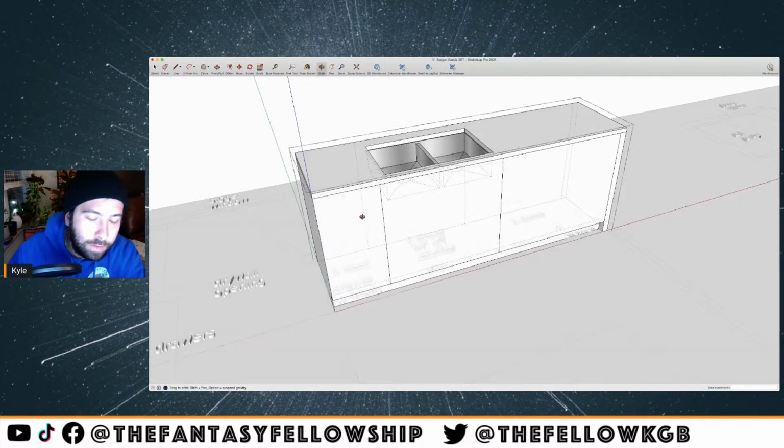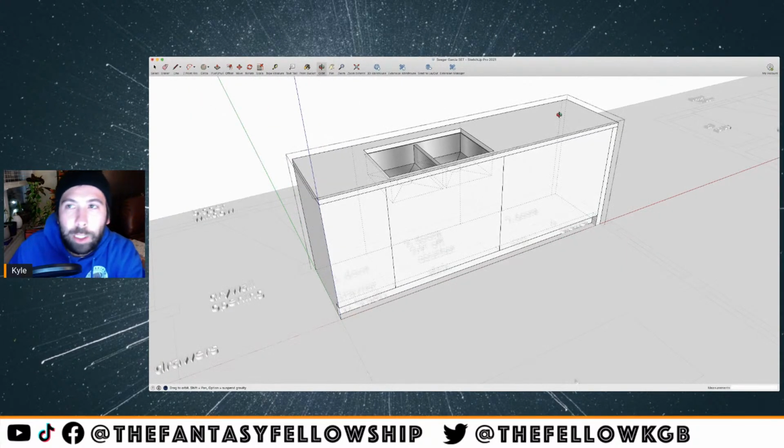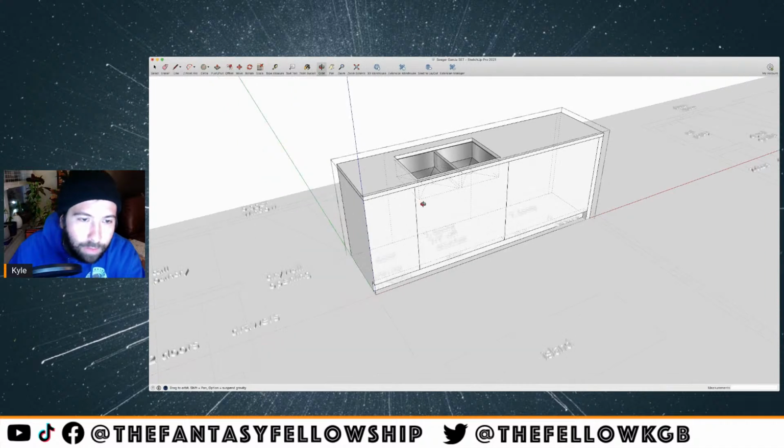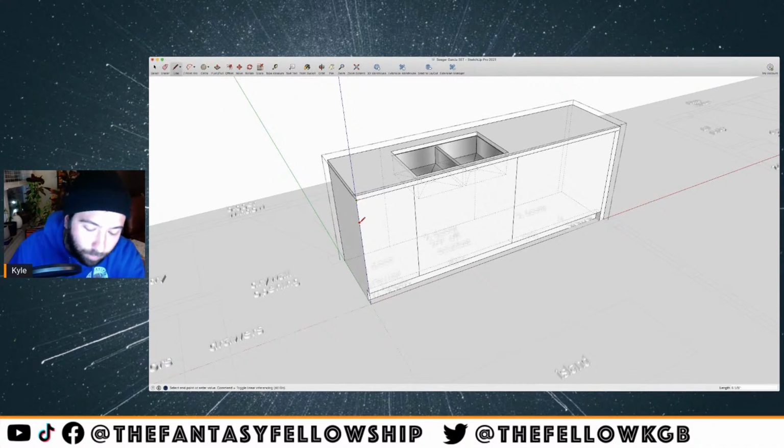And I'm going to draw these cabinets. I'm not really caring too much about the accuracy of the cabinet. I'm going to make it look real. But she called for a drawer with a trash here. So I'm going to come down 6 inches for the top drawer. There's going to be a false drawer here above the sink. And if you toggle that there, she wants 2 doors below the sink. And then that's going to be your trash pullout.